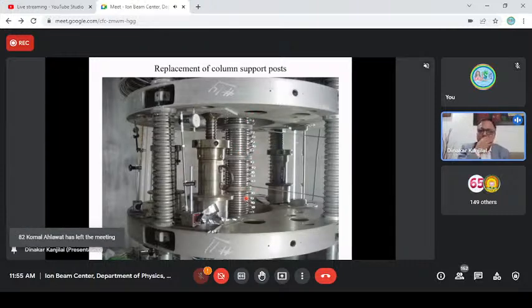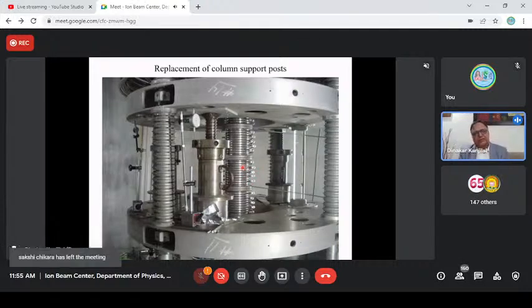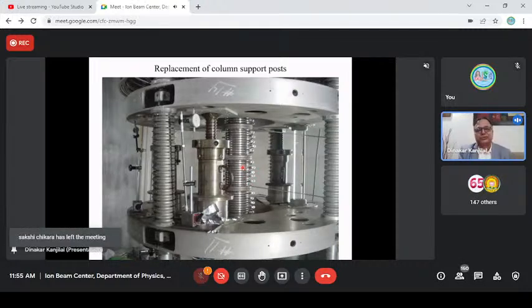And this I want to show, because it is a new material. What is the material? It is actually titanium and ceramic. Earlier, when accelerators were built, there used to be glass between the electrodes. This was a new development. Titanium and ceramics are put together at high potential and high vacuum, and there is solid state diffusion. You will study this when you go deeper into solid state physics. In solid state diffusion, the atoms start diffusing at the interface, and that bonding is permanent. No glue can bond like that.